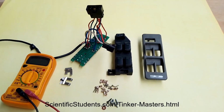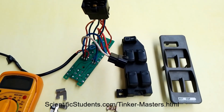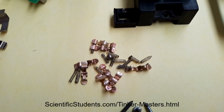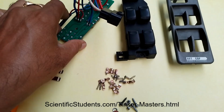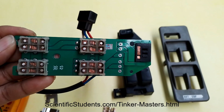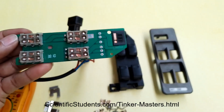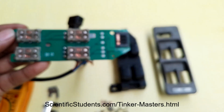What I wanted to show you is there is a double-sided PCB, and there are switches. And these are the ones connecting the contacts of the switches. I will show you the contacts of the switches here. You see, they are the contacts of the switches. A lot of dust went into the switches. So I opened all this, cleaned it totally, and removed all the dust from the contacts.